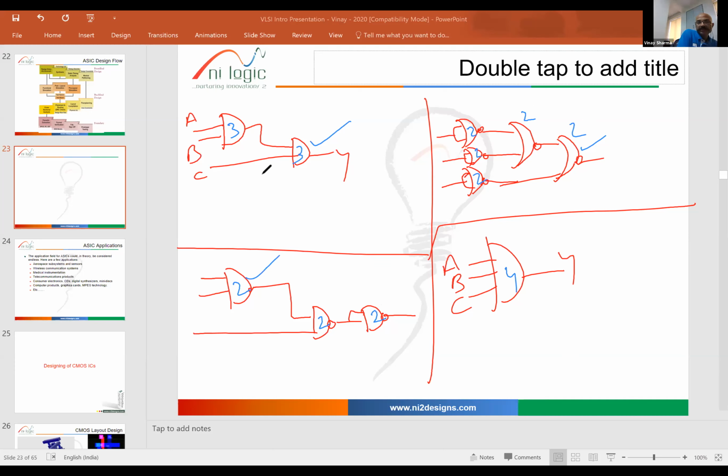Well, it's based on this. Now here, if I see, the delay from A to Y is 6 nanoseconds, because this is how the delay passes through. This is how my data passes through from here to here, right? So the delay would be 6 nanoseconds. My delay from C to Y would be only 3 nanoseconds, but I would be working on the 6 because designs work on the slowest path possible. They don't work on the fastest one.